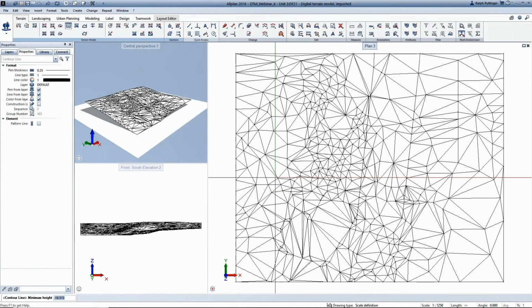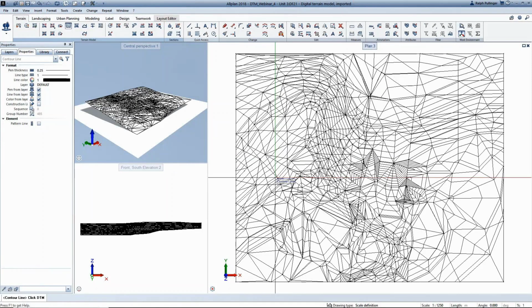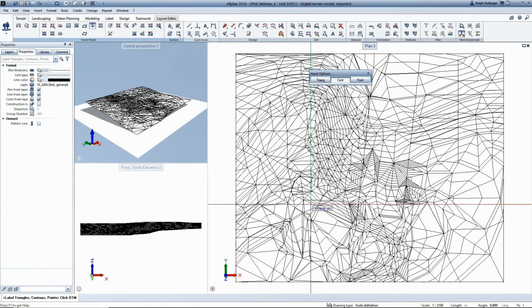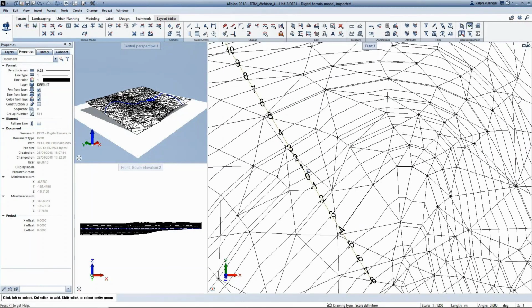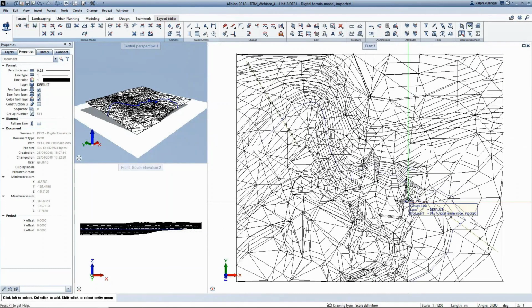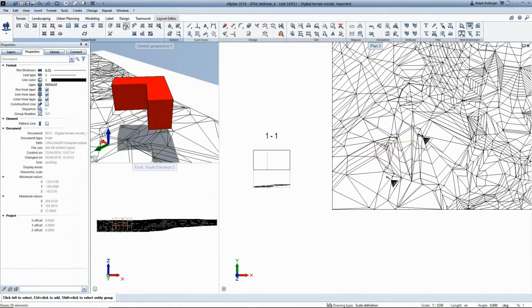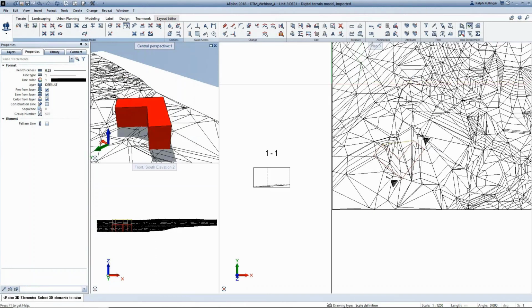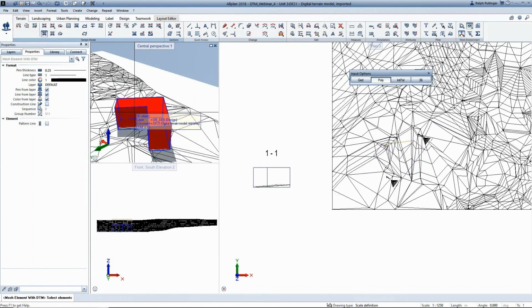For instance, we can look at contouring. We can take our digital terrain model in the background and place lines or polylines at 3D elevation. They are derived from the points in the digital terrain model. We don't do interpolation at this point, so these are fairly sharp contours, but we can employ contour smoothing if we want to. Then we can annotate those contours by selecting the contours we want to cross and putting numbers against them for their elevation.